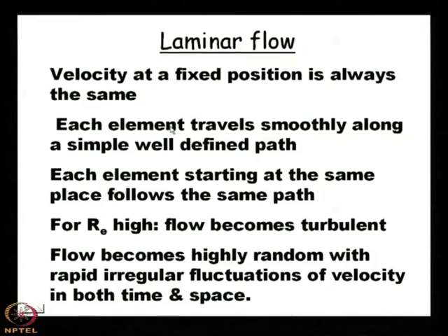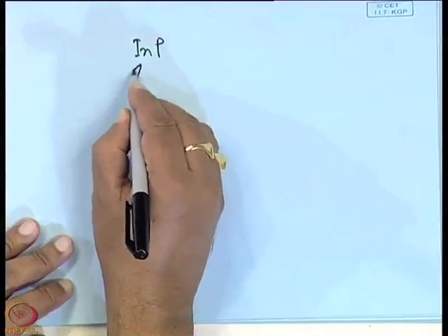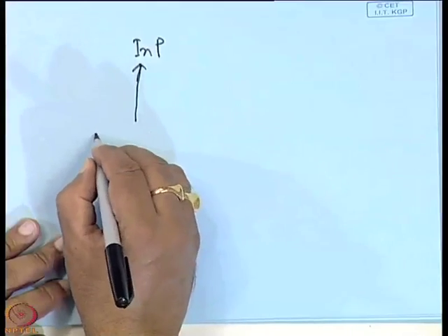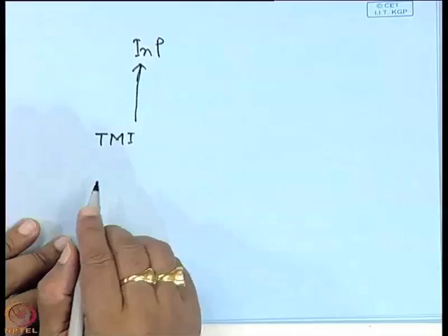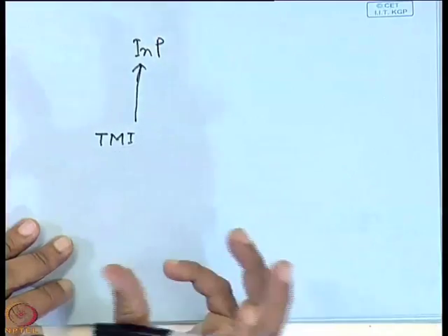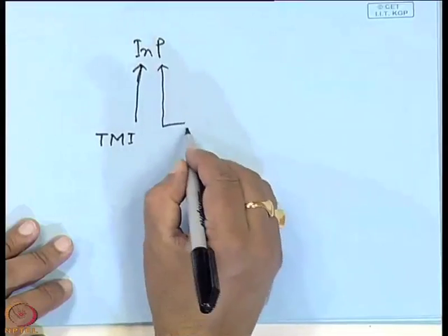That means, in the gas molecules, what should be the molecules? One type can be, say for 3,5 semiconductor growth, it can be the molecule of the trimethyl indium. Say you are growing indium phosphide. So, for indium, what is the precursor? Trimethyl indium. That is why it is organometallics. Trimethyl means it is an organometallic, trimethyl indium, and for phosphine.